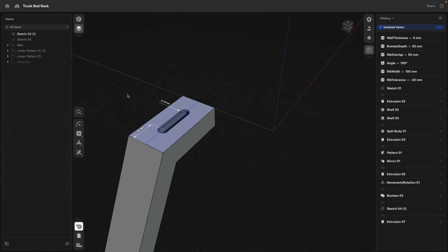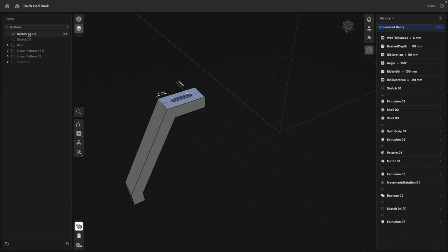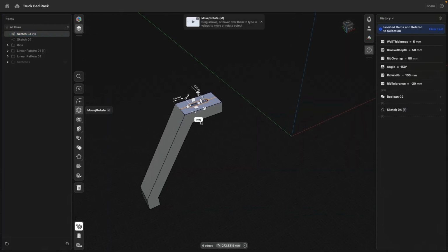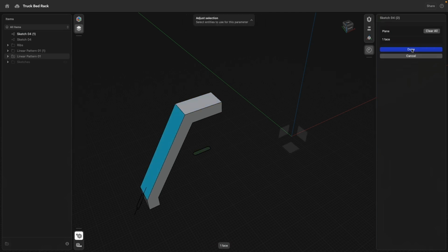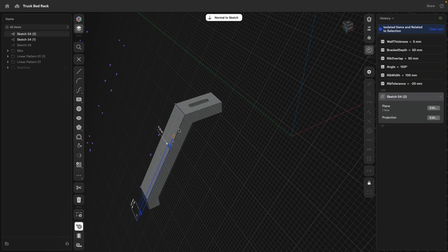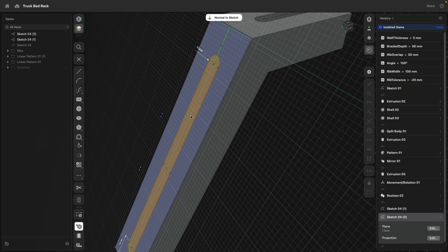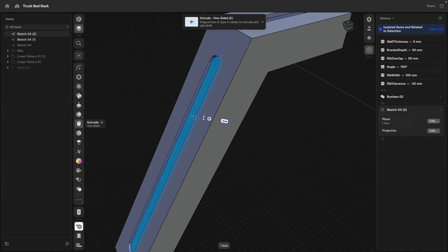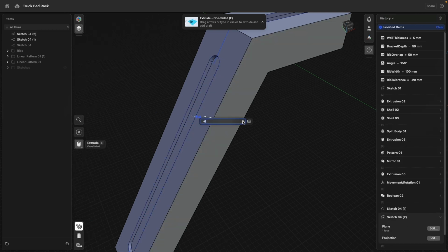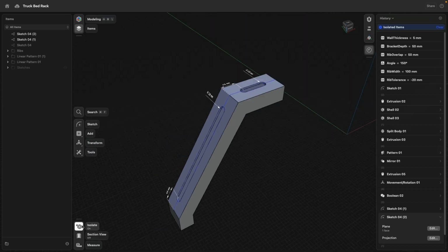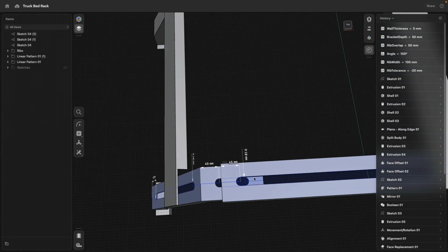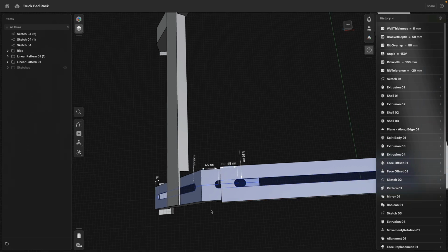Perfect. Cool. And since we are in this mode, I can select the sketch, make a copy. I can simply move this down a little bit and then say here, project onto that face, move this one to there and there. So it's actually quite nice to recycle our sketches instead of having to recreate them. Beautiful. Okay, unisolate. You see now here, this looks actually quite nice.